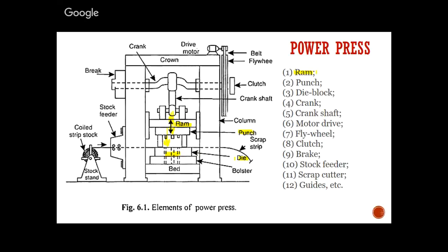The hole has the diameter of the output we require. The hardened and tempered die block involves the actual cutting or shaping process. That's why the die and punch are both very important for sheet metal work.